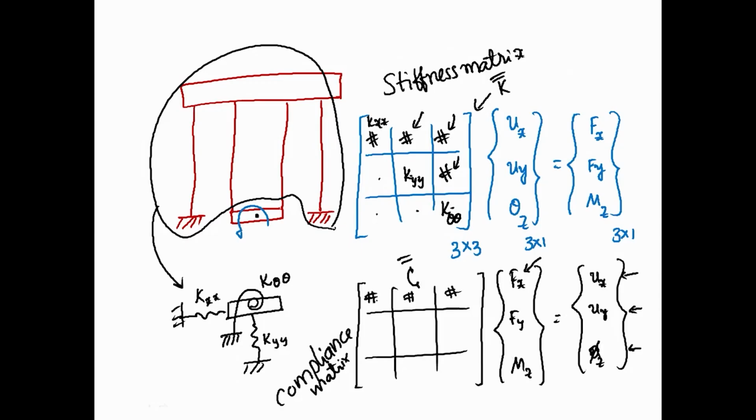For that I will get this value, and when I apply this, what I need here, when I want to get uy, I take the second row and multiply this. When I do that, this is a symmetric matrix, that is, this value will be same as this value, this multiplied by that will give me ux. Okay. So, I need to do 3 finite element analysis runs in a 2D case, apply force as 1 Newton there and other things are 0, and then another analysis where I apply this 1, other to 0 and apply 1 Newton meter here, other to 0, 3 finite element analysis, which is what we will try to do now.